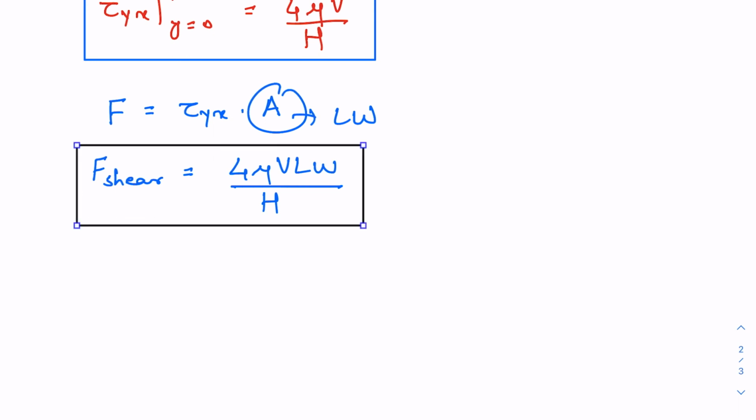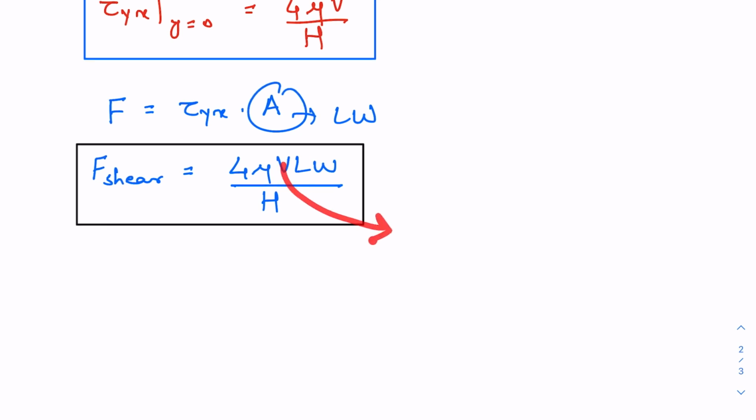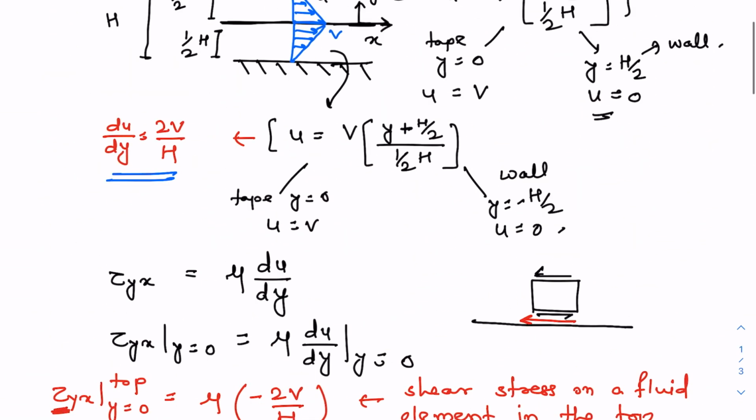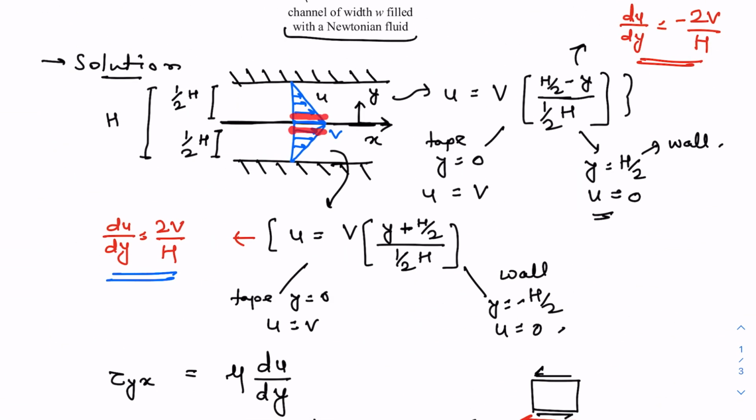So as you can see, if we pull the tape out at a very high velocity, we will have to apply a very high stress because of the viscous stresses on the tape, due to the velocity gradients and the no slip boundary condition at the surface of the tape.